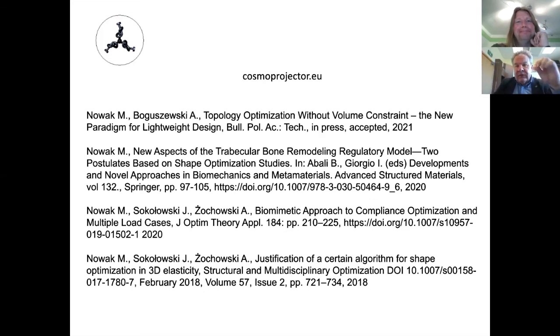So we assumed right from the start that we want to avoid these problems, and in our approach, every step of computation uses a different mesh. So I have two models. One is for finite element modeling, where I just produce the mesh for computation. And the other one is the evolution of the geometry. So this is completely separated.